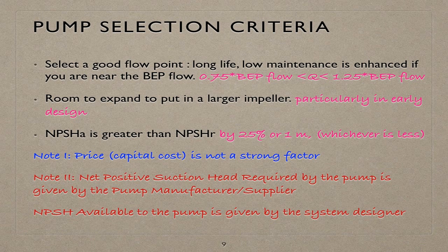The last but not the least is net positive suction head. In order for the pump to move fluid, the system must be able to push fluid into the pump as fast as the pump can push it out.